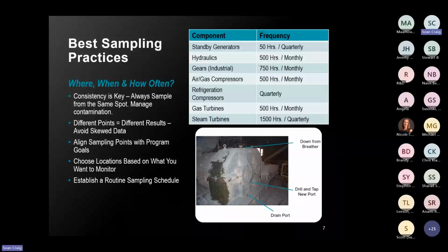Typically, for large turbine systems, the oil can go in there for a decade or two decades. Very common. They're trying to monitor whether they can get another year or a few months out of it, so the oil replacement takes place during a more convenient downtime instead of the middle of summer at peak demand hours. You can set it to the fall and ask, can we push it that far? That's a quick goal.